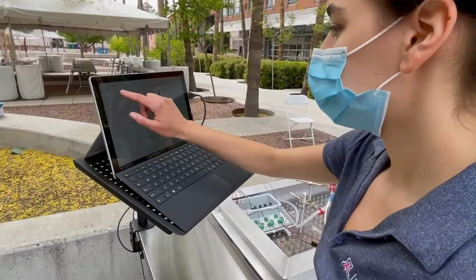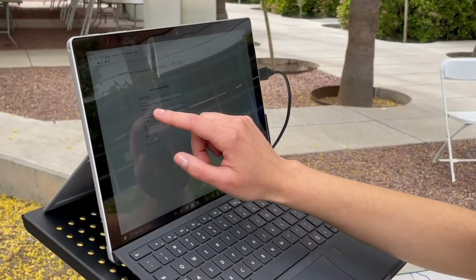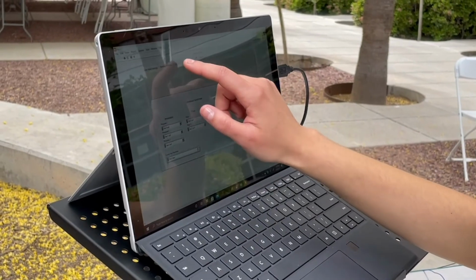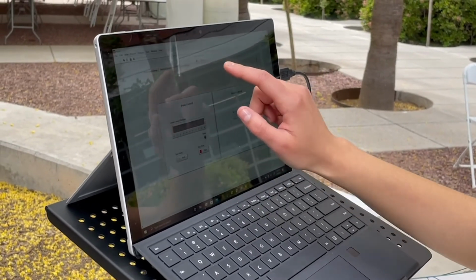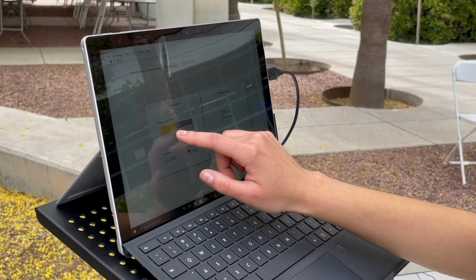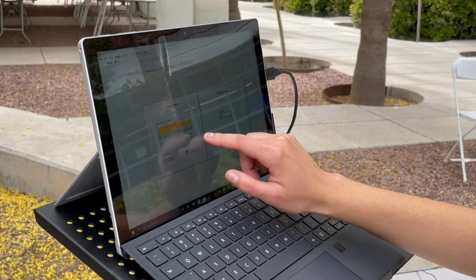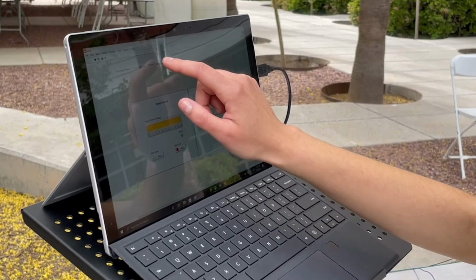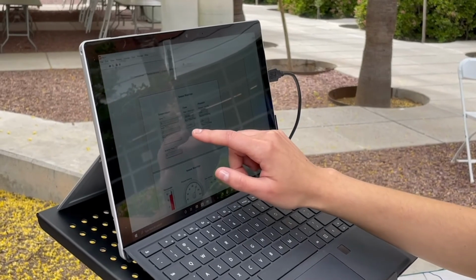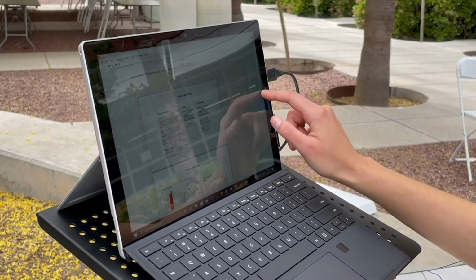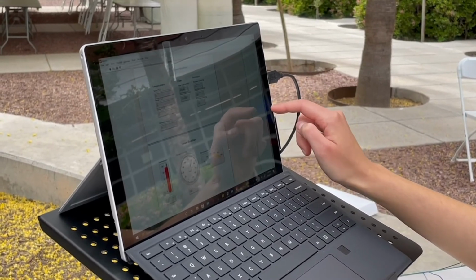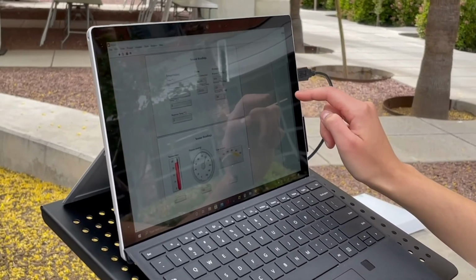To regulate the parameters of temperature, flow, and pressure, PID controller feedback loops were integrated into the software. This PID regulation begins with the sampling of sensor data. These readings are then processed through a PID algorithm. Then control signals are sent to either pump or heater to complete the loop. Temperature is regulated in this manner. Due to the limitations of the current pump, the parameters of flow and pressure are not regulated in the current system, but the groundwork has been laid for the sponsor to use a more capable pump at a later time.